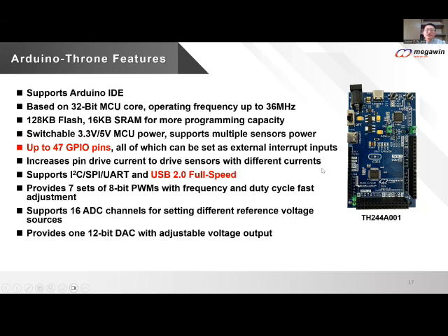So it means the driving current of the I/O is programmable for different kinds of applications. So if you want to save power, or you want to have lower EMI, then you can choose the lower driving current.